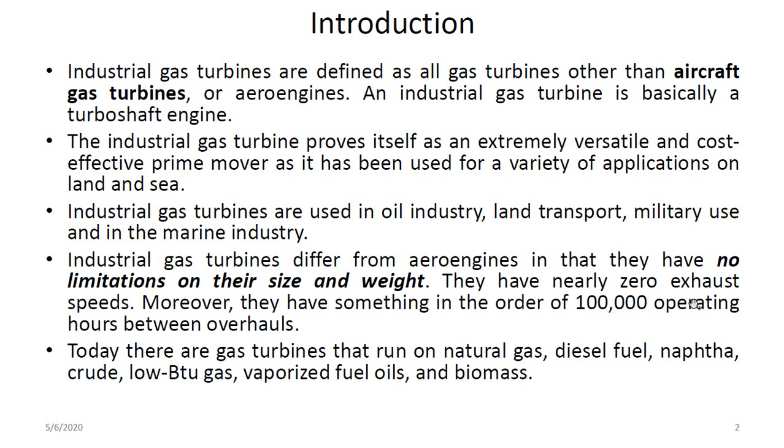Remember that in the aircraft business, weight is something that you would want to minimize. So anything that is heavier will have a weight penalty attached to it. So with this, you don't have to worry about weight and size. Okay? And the good part about these gas turbines is you can use a variety of fuels: natural gas, diesel, even biomass.